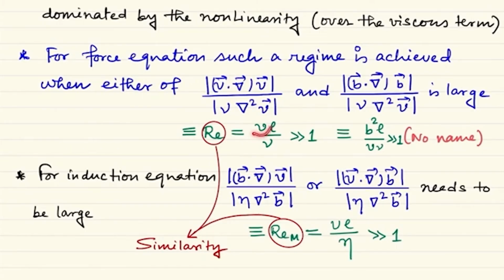just by choosing the corresponding velocity and the coefficient of viscosity, you can simulate it. Or just by doing the inverse thing, that means you can choose the length scale to be 10 times smaller, but again by smart choice of velocity and the coefficient of viscosity, you can again simulate the fluid flow with the same type of property. That means you will again see that when the Reynolds number is of the order of 5000, then in that system you can produce turbulence directly from laminar flow, okay.